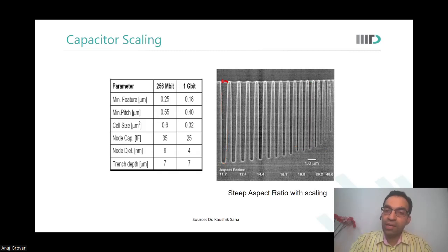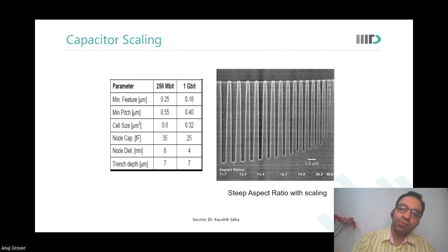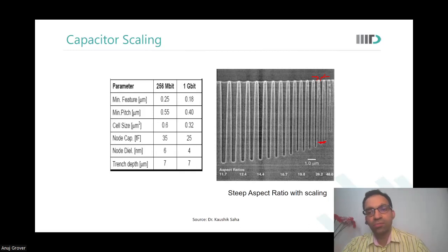But it is important to understand that if area is the primary thing, then you can do something more about it by doing away, for example, with the depth. So area is the main concern over here. If you reduce the area, you therefore end up reducing the depth and the capacitance value. So area and capacitance are a direct head-to-head trade-off.